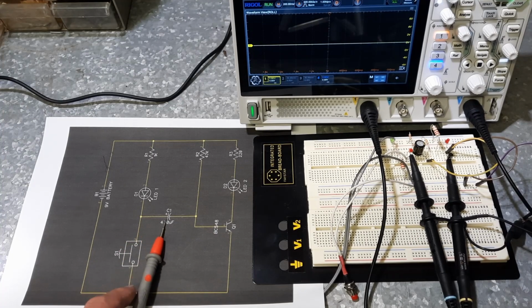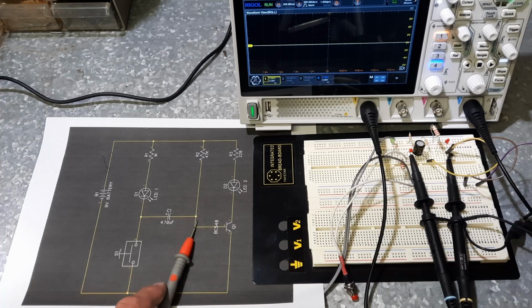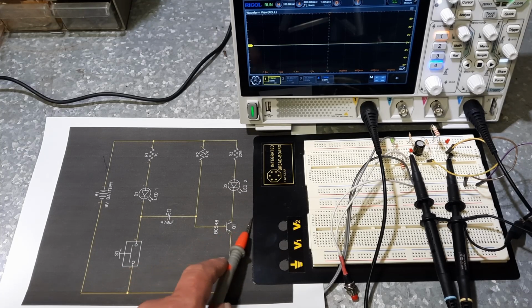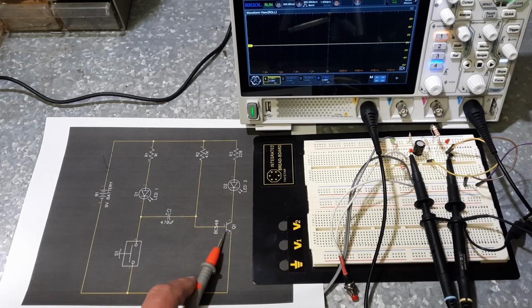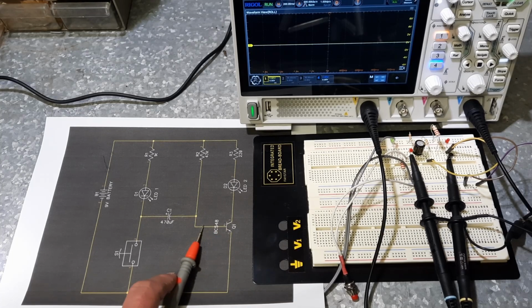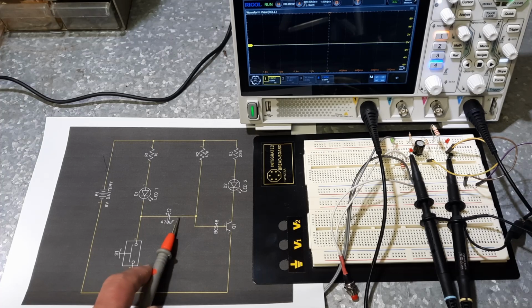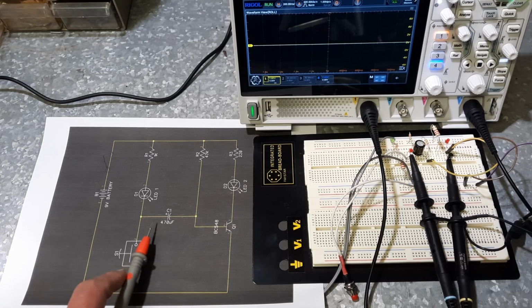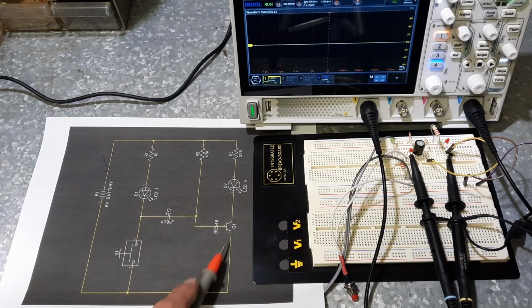Once this has risen to 0.7 volt on this side, this transistor is going to then saturate again. So this is with me still holding this button. This will rise up from its negative, it'll pass through 0 and rise to 0.7, and then it'll flatten out. And this will hold it at 0.7. So this capacitor will never see more than 0.7 of a volt reverse charge. But this will then become saturated again.